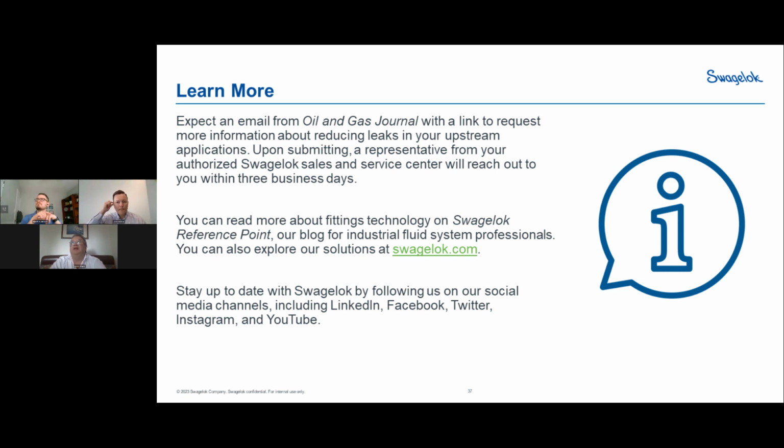Digging into a little more detail, somebody asked, if I were to use a different alloy tube with a stainless steel fitting, is the tube fitting still rated for up to the tube design pressure? I'll take that one, John. Great question. In general, we call that an engineered combination, since you're using a different alloy tubing with a stainless steel fitting.